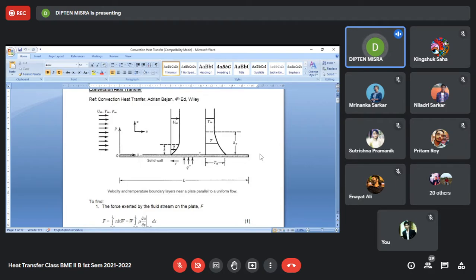Yes, sir. That is what is being attempted to be addressed over here, how to find out the value of H. And when we talk of finding the values of H, we are not concerned about the solid as a domain of interest. Now we are interested in the fluid as a domain, with the solid as a boundary. So what type of boundary condition on the solid will be there? That can be an isothermally heated solid wall. It may be an isoflux condition. It may be neither isothermally heated nor isoflux type of wall condition.